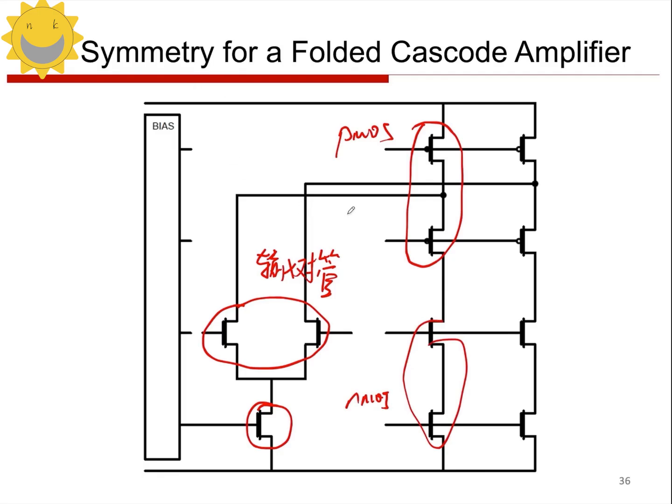This is the load capacitor for the operational amplifier, as the output impedance provider for this operational amplifier, right? Now, let's take a look at this current source part. The PMOS here is a current mirror structure, right? And below it is a common source transistor.